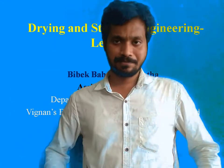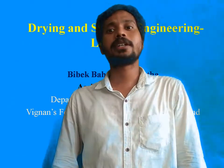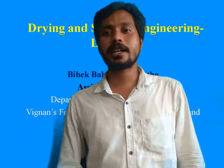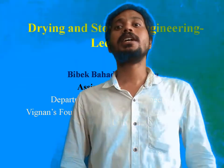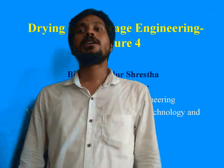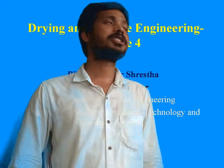And then we had a discussion on equilibrium moisture content models. We had several models available, but out of these the Henderson equation is the most popular: 1 minus RH equals exponential of minus C into T into Me to the power N, where C and N are constants that depend on temperature, RH is relative humidity in decimal value, and Me is equilibrium moisture content in percentage dry basis.